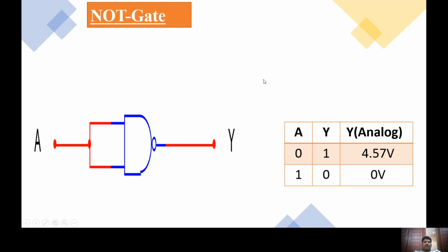So this is the trainer that we have already seen in our laboratory. These are the inputs. These logic inputs mean either 0 or 1. Here, one button will be there. If you move this button downwards, it indicates logic 0. If you move that button upwards, it indicates logic 1. At the same time, if you move this button to the top side, this LED will also glow.